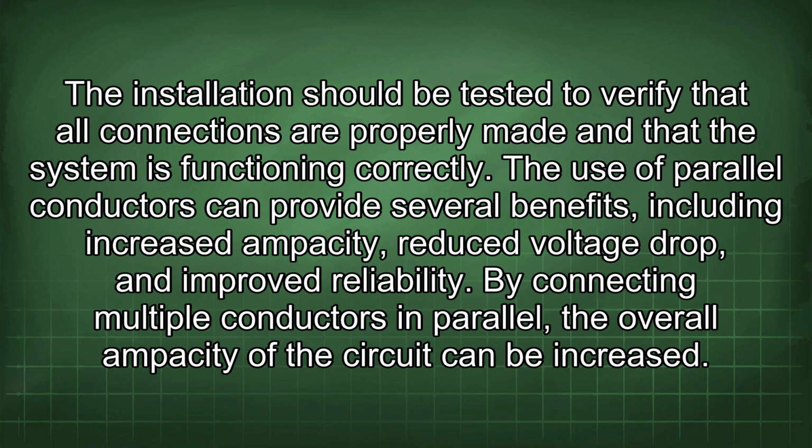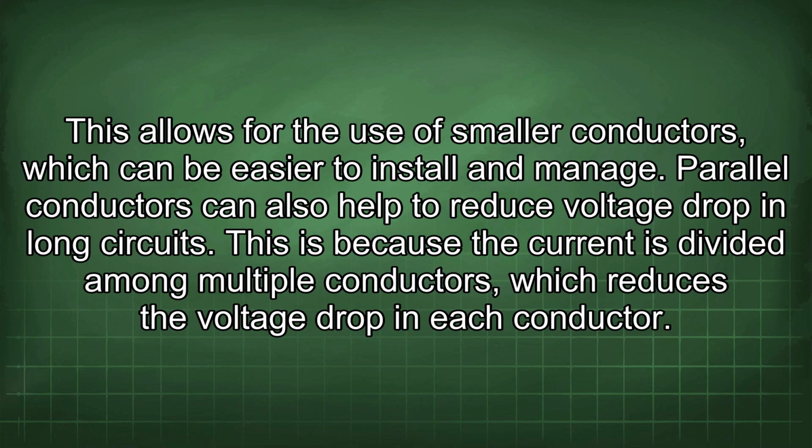The use of parallel conductors can provide several benefits, including increased ampacity, reduced voltage drop, and improved reliability. By connecting multiple conductors in parallel, the overall ampacity of the circuit can be increased. This allows for the use of smaller conductors, which can be easier to install and manage.